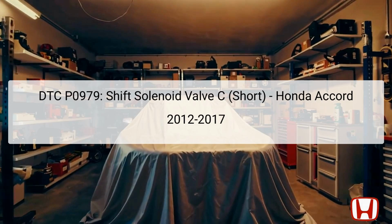The Diagnostic Trouble Code, DTC P0979, indicates a problem specifically related to the Shift Solenoid Valve C in the Honda Accord models from 2012 to 2017. This code is triggered by an electrical circuit problem, which means it points to issues in wiring or connections, rather than mechanical failures within the transmission itself.